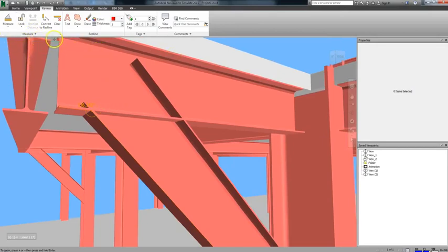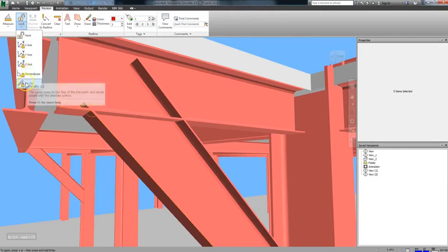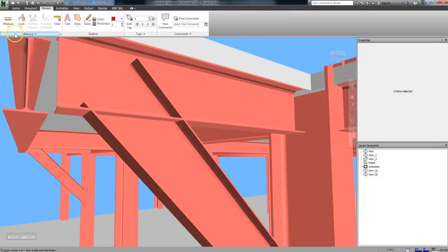Okay, now let's try doing another point-to-point measurement. But this time, we're going to use the lock feature. This lets you set a starting point, and then the line will only move in the chosen axis to which you're locked. So that means you can take a starting point and then measure along the x-axis, the y-axis, the z-axis, perpendicular to that point, or parallel to it. We'll show you parallel for this example.